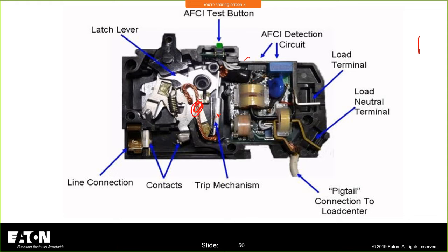This little rope can get a little bit warm. And then if you look right across the face, look what's coming down right across the face inside of this breaker. You have the conductor that's got to go through this CT, and look at its proximity to the front of that breaker. This conductor is going to get a little warm. And if you're doing a thermal scan, you'll not just see the face of this breaker. You're going to see what's heating it directly behind that face.